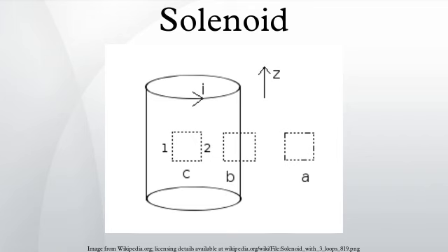The terms relative permeability and effective permeability are often confused. They can differ by many orders of magnitude. For an open magnetic structure, the relationship between the effective permeability and relative permeability is given as follows, where K is the demagnetization factor of the core.